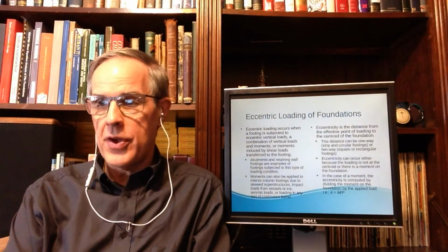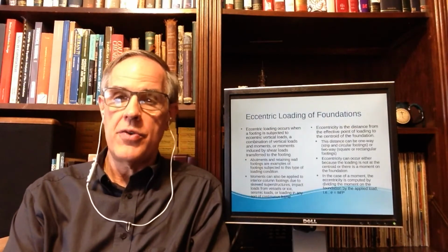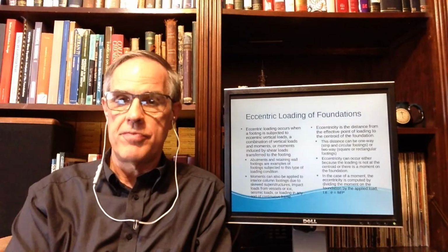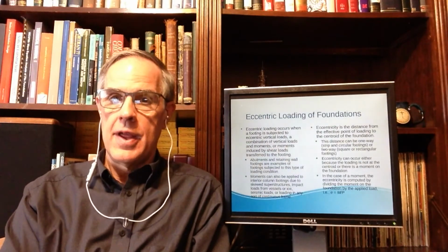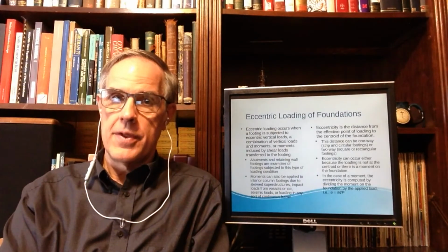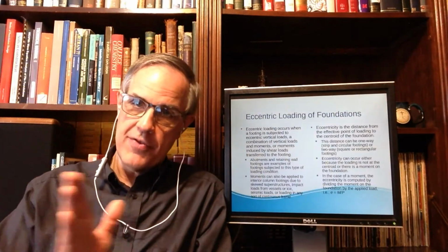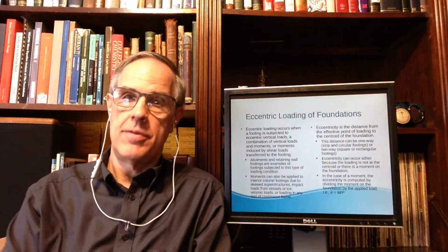If it's just axial loads, down loads like that, and they're not in the center, that's eccentric. But even if a load is concentric and there's a moment, the moment can actually shift the resultant of that load off center.